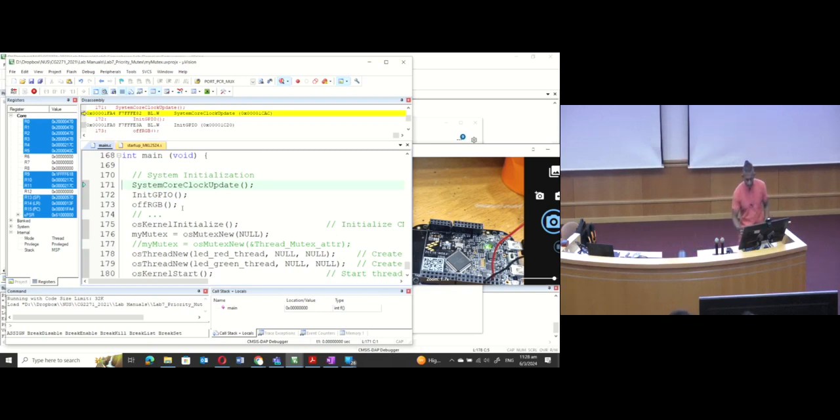So here you try to lock one more time, but it will not allow you, so you will become blocked all the way. Eventually both the tasks remain blocked indefinitely, and that's why you do not see any other LED behavior.